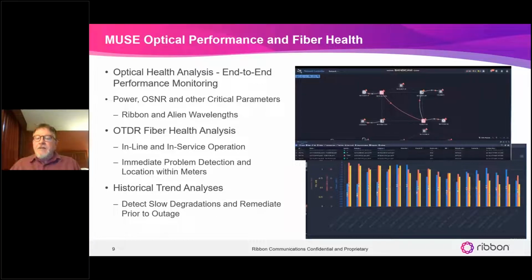And so the ability to monitor all of those signals for all of their critical metrics, and then set alarm thresholds on them. So if over time, say for instance, your transmit level is dropping, now it's still passing traffic, and so you haven't got an outage alarm yet, but it is declining, it is degrading over time, something you might want to take a look at. And so this gives you that extra visibility at a deeper level to understand what's happening, not just now, but over time, so you can do preventive maintenance, right, to avoid outages altogether.